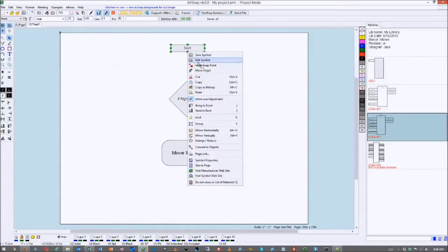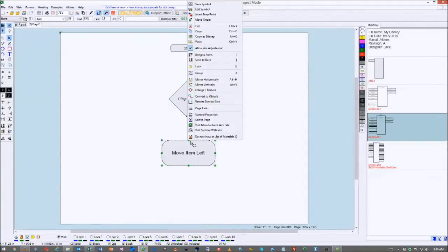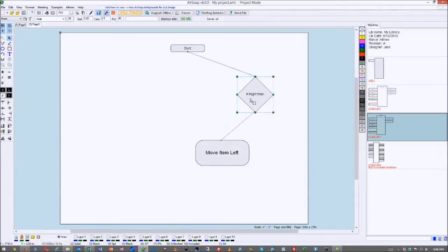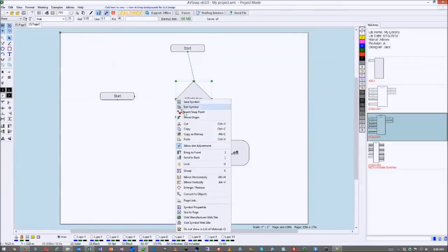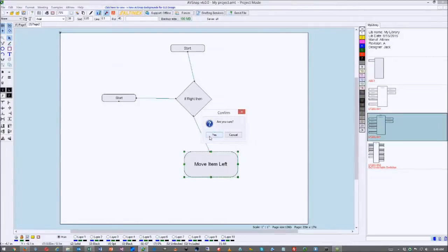And then you can add snap-in points here, okay? I'm just going to add a bunch of snap-in points. And right here you have a feature in the flowchart mode. Once you switch it to flowchart mode, it automatically tries to connect things together for you. Can you see that? And if I create another block here on the left-hand side, and I put a snap point here, and a snap point here, it will also try to connect it. Now, once you put the flowchart together, you can right-click and say auto route flowchart, and it will automatically route the flowchart for you.